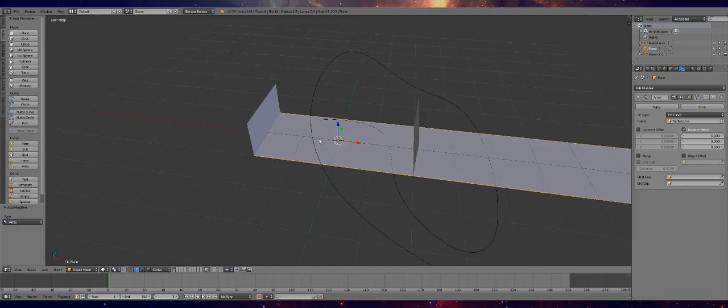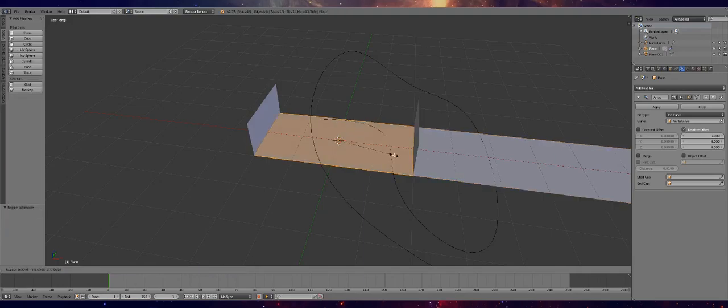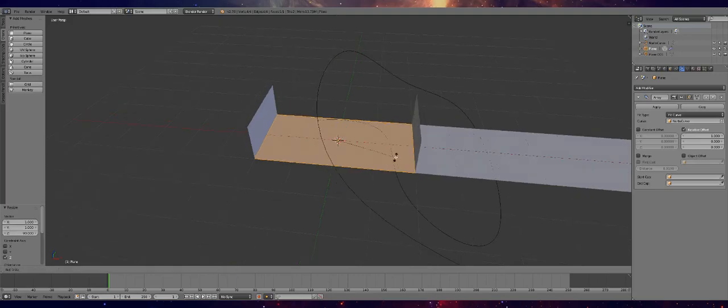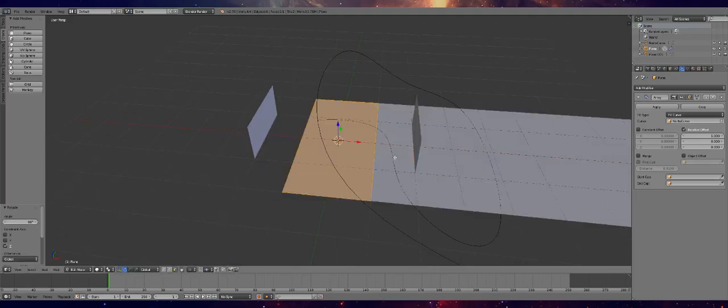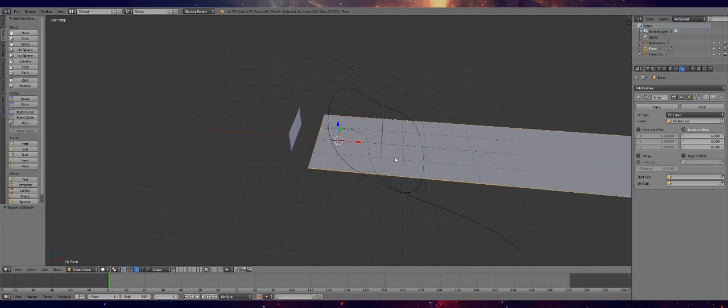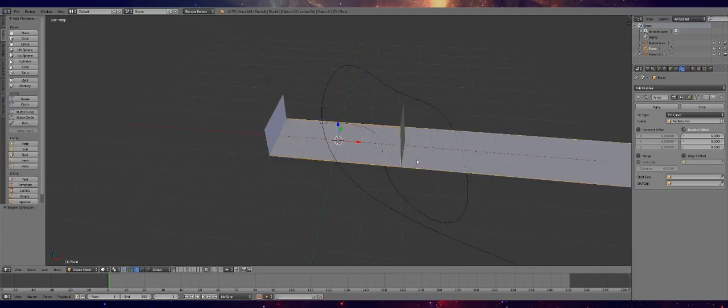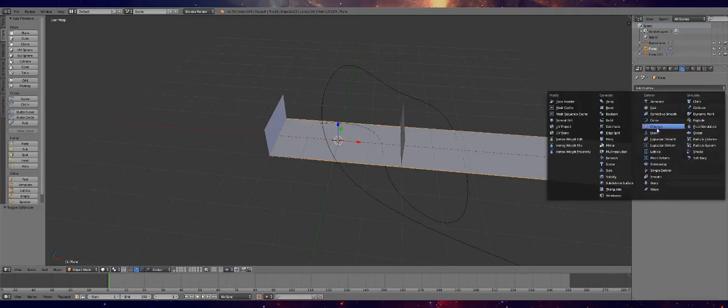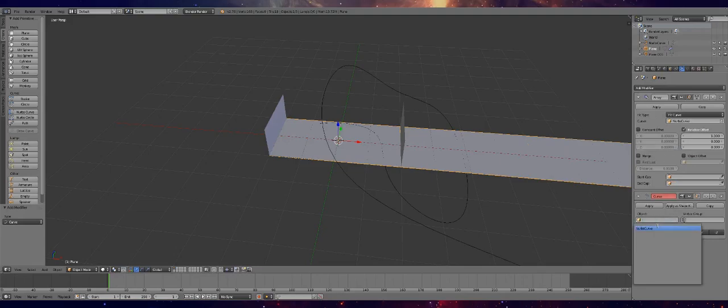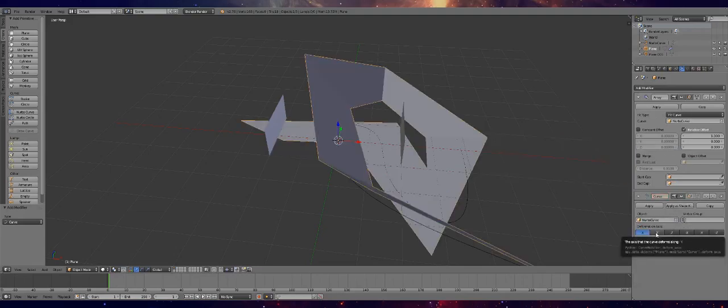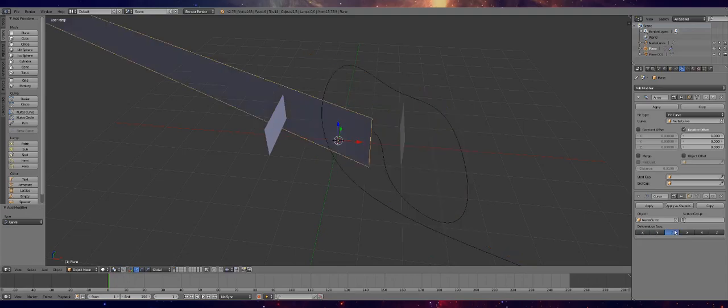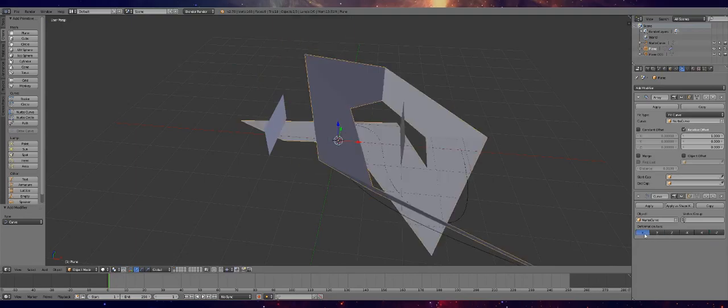There are 2 ways you can fix it. You can either hop right now into the edit mode and rotate around Z for 90 degrees, and that should fix it. Or you could leave that be and fix it in the next step. If you want to fix it in the other step, you just add curve, and then instead of selecting X, you would do Z. Sorry, you test the other options until you find something that works.